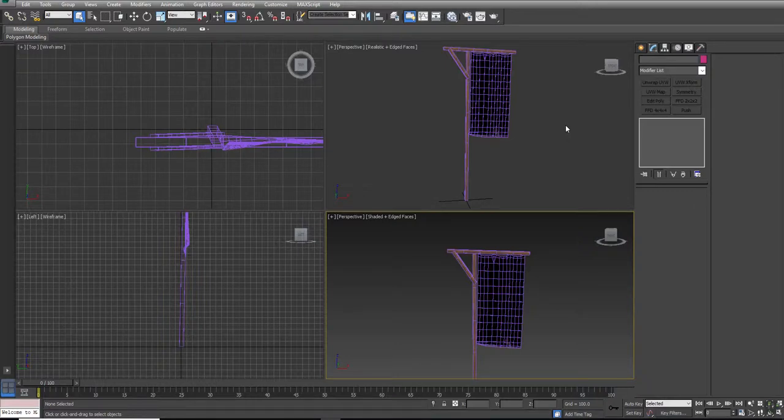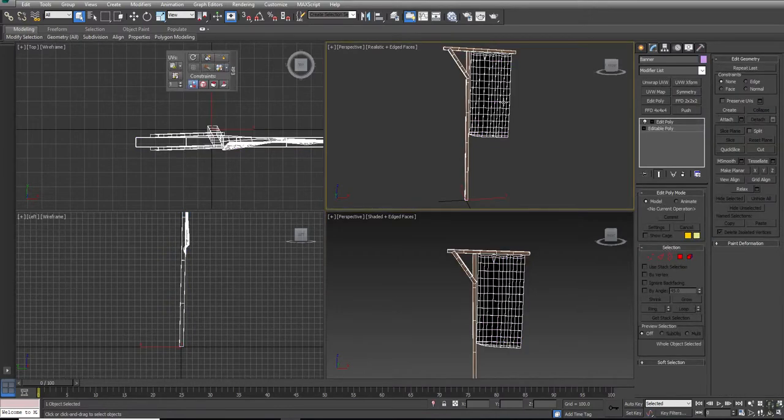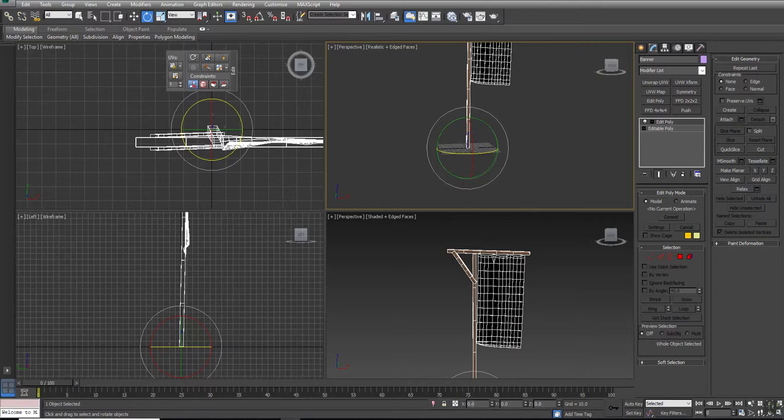Alright, I'm going to show you the basics of placing an asset into the Unreal Engine. And really, this process of actually getting your asset out in such a state where it could be used in any game engine. Everything is attached as one mesh. The origin sits at the origin of the world, located at 0, 0, 0, x, y, and z. The rotation has no value on it, and the scale has no value on it beyond 100%, which means full